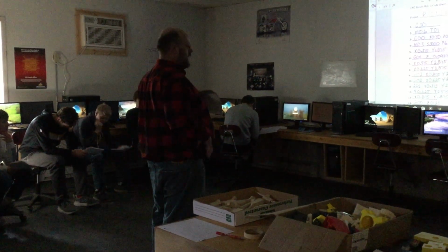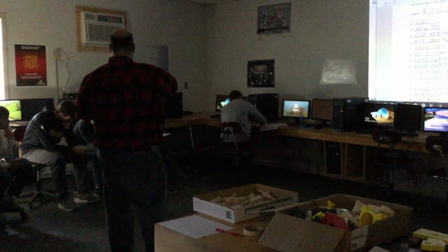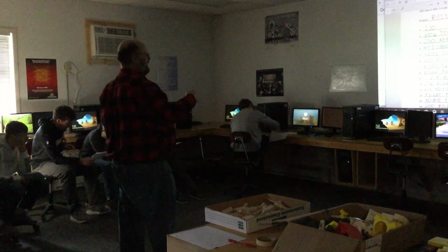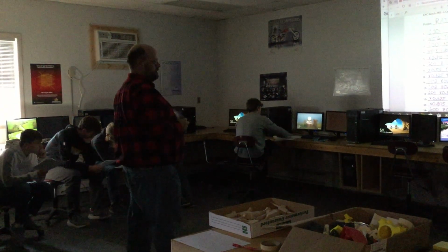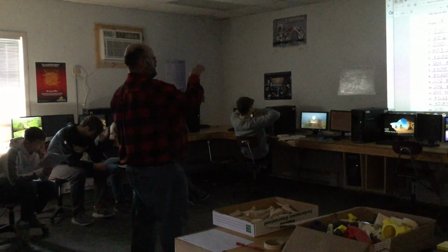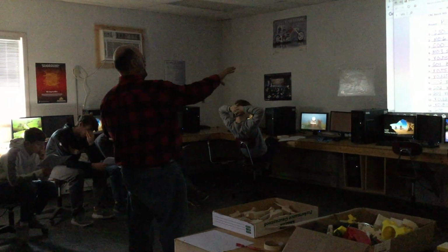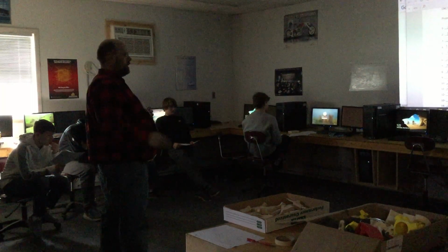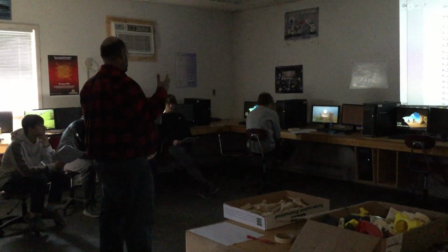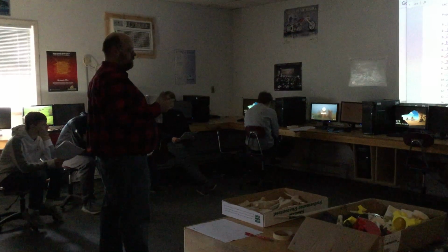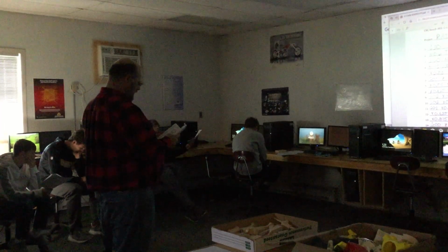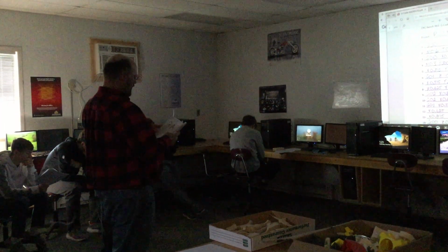So your radius could change depending on where that second point is. You could have an 1/8 inch radius, you could have an inch radius, depending on where that second point is. But with this machine, if you put G02 and you just put the X, Y, and leave out the R, when it gets to that step on the computer, it's just gonna stop. It's gonna tell you incomplete location. So that's kind of nice. But then you have to go back and figure out where you messed up, what you forgot. As you go through this, I have all those listed there, so you can see where all those went.